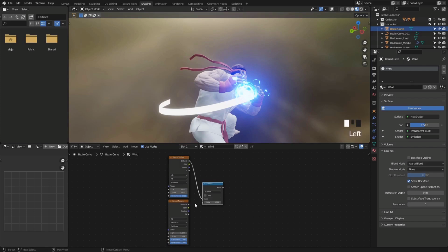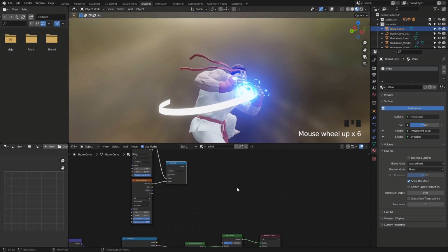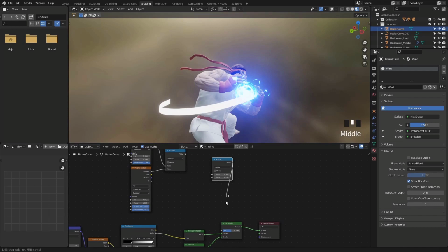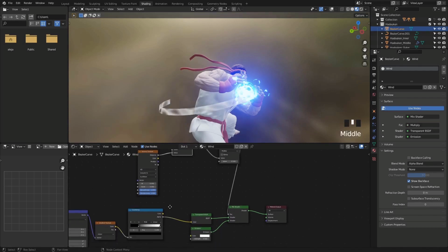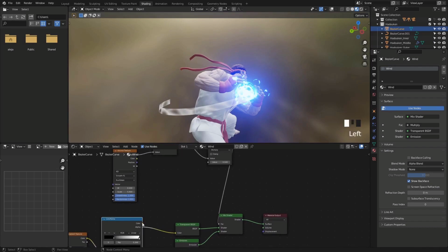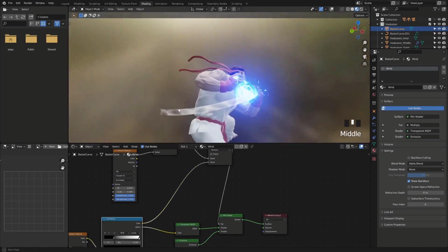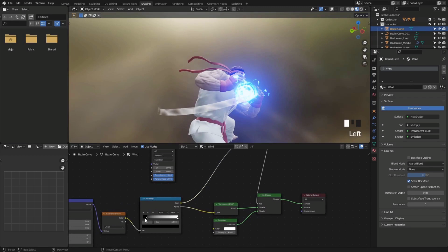And I'm going to connect the distance outputs right here to there. It's basically what we've been using before. I'm going to go ahead and make another math node, make this multiply, so that we can multiply the work of the gradient to the texture here. And for this purpose, let's just start with color. And as you can already see, we're seeing some results. And there we go. So as you can see, we're starting to get some gradient work happening here.